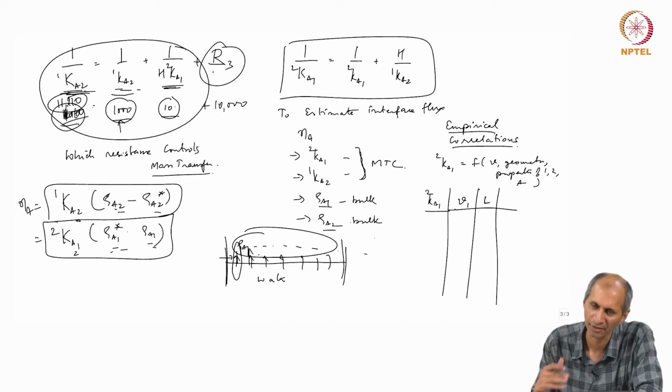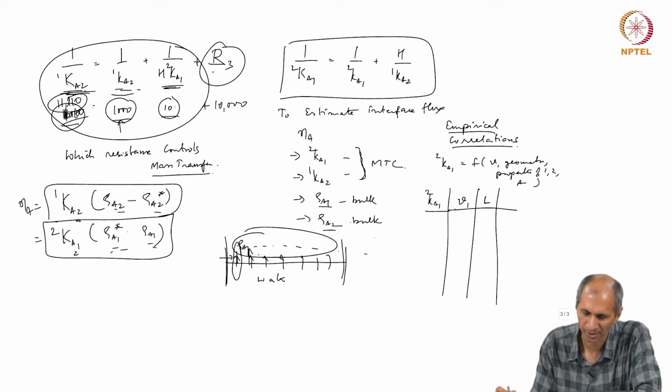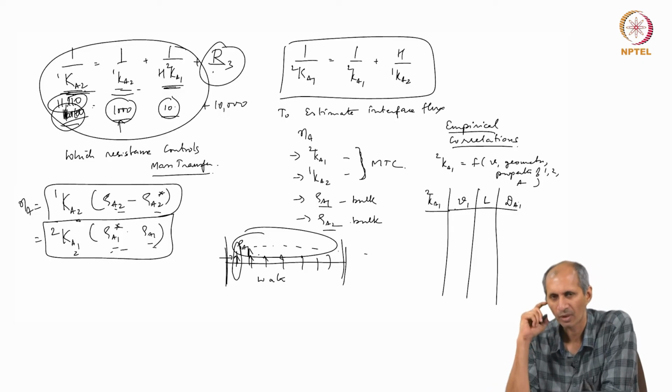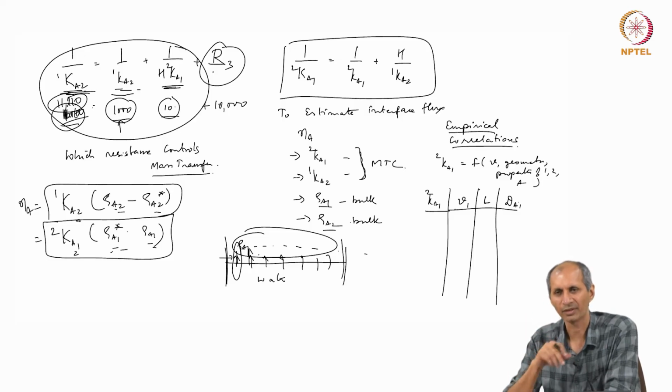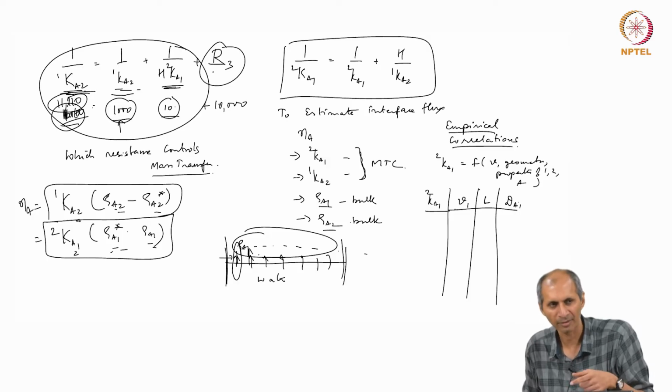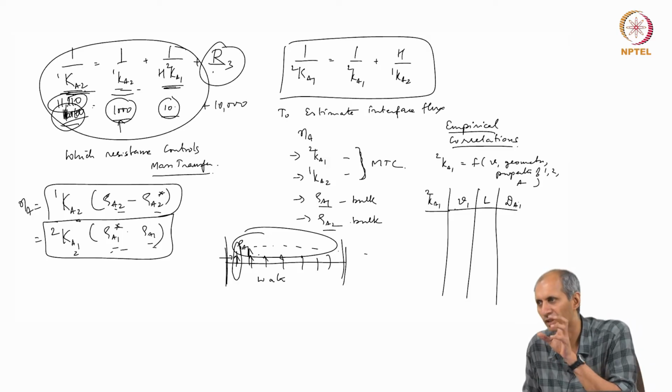It is true again with different other mass transfer systems, we will not discuss it right now, but if you are from a more general mass transfer coefficient concept, that may be important. And we also have the diffusion coefficient of 1, dA in 1. This is important because we have also mentioned earlier that the mass transfer coefficient is a combination of both convective and diffusion terms.